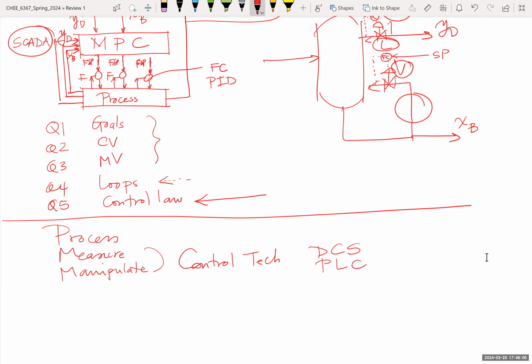So data would be transferred by telephone lines there. The results would be transferred back by telephone lines. There would be a printout, and the operator would key in set points to a system. This would be at this level, roughly. Okay? But that would be a central computer, so systems were centralized. When DCS came out, everything was decentralized. Why decentralized? Because now you could buy a PC, and you could buy a few of them, actually, and they're very cheap, and you could put them around the plant in various units. You have your local decentralized control system. Okay, so there's plenty of jargon on this. These are some important names that I mentioned here.